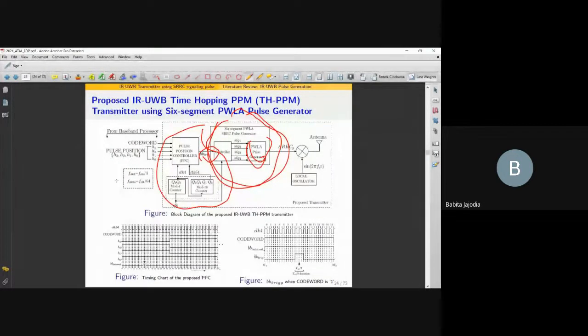Okay. So here, a question can come up, ma'am, as you mentioned, that they don't require any local oscillator, etc., right? But we are representing this as we have taken the bandwidth of 500 megahertz only. And this was a specification given by the standard that when you are using only 500 megahertz, you have to multiply it with a local oscillator. Else it can't reach the particular band, because this is the baseband generated here, right? So these are the things from the baseband processor.